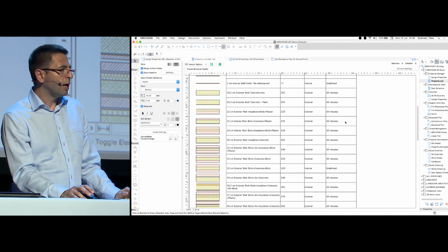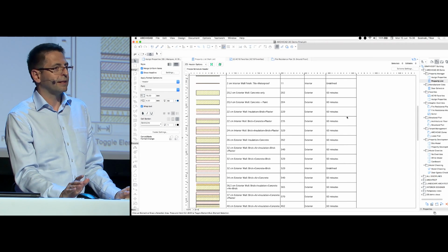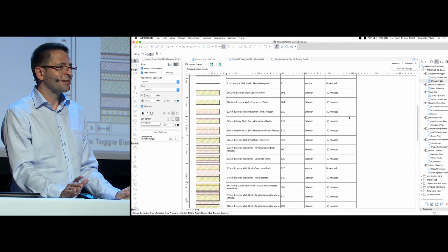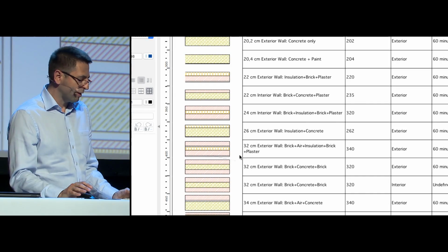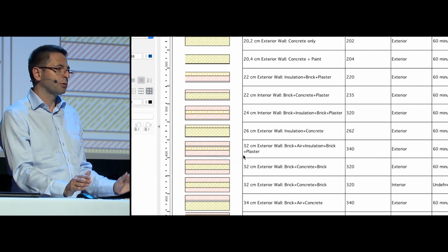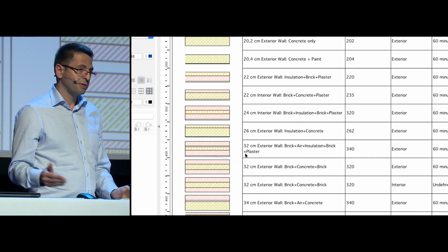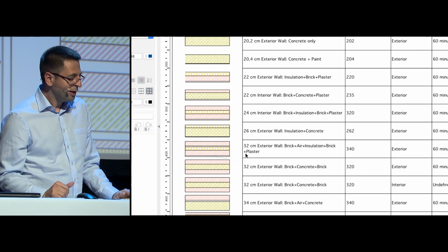So that's very good. But if you're a long-time ARCHICAD user, you can also notice something else. Are there any ARCHICAD veterans in the room today? I can see quite many. So probably I've already noticed what I would like to show you. These are these beautiful previews over here. These previews have been available for interactive schedule in previous ARCHICAD versions too, but only for the library parts. In ARCHICAD 20, we opened this capability for all the tools, for the walls, for columns, beams, and I think this is not just beautiful, as I promised you, but it's also a great way for communicating with other parties, so it makes the communication more straightforward, less errors, and more streamlined.